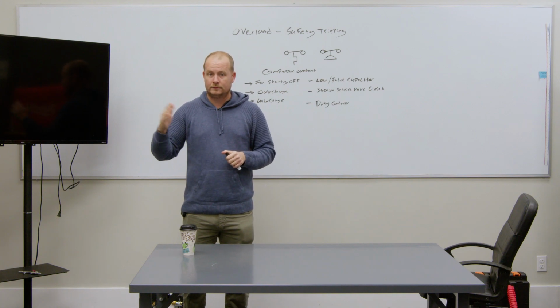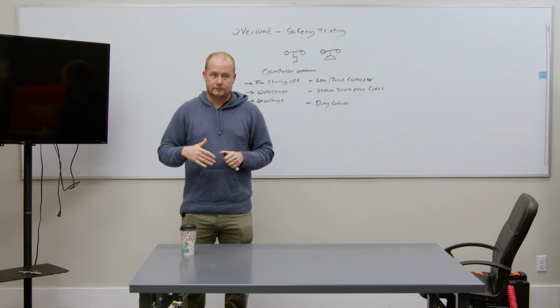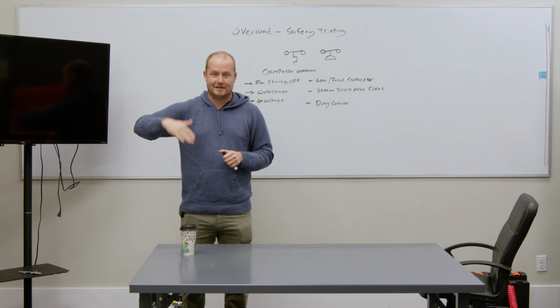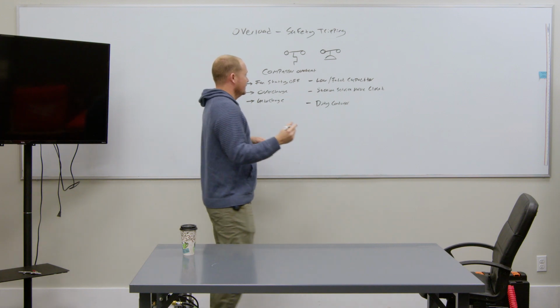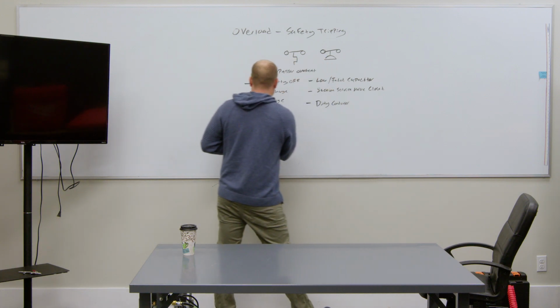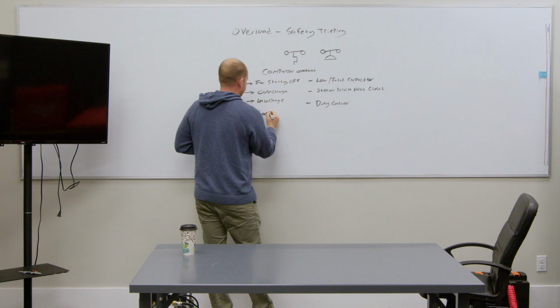You hear that, that kind of thing that it does, and I'm doing this. This is the amperage going up. See, that's what this is. That would be a locked compressor.